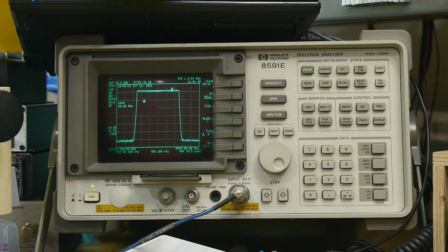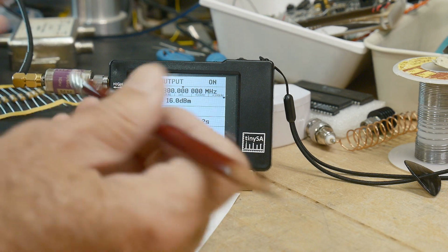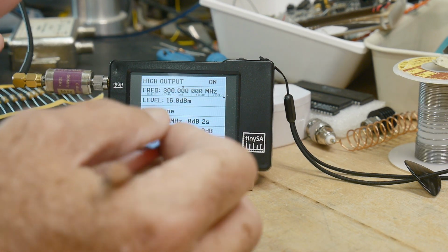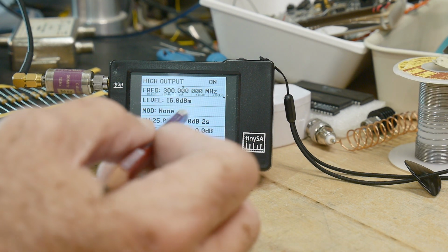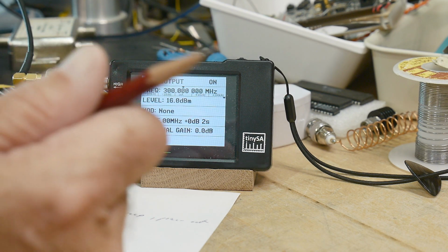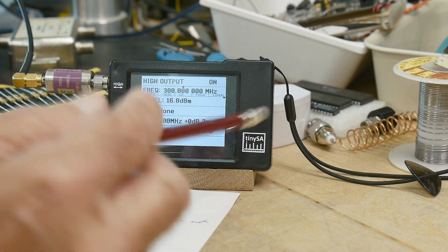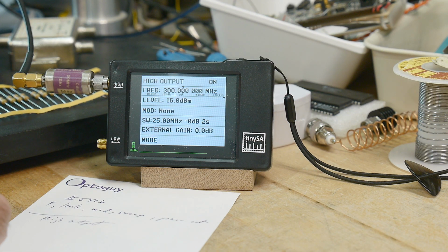All right, so I think that's all I'm going to show in the video here. It is a very nice RF generator. It comes for free with the TinySA, so you know, you can justify buying this just for the generator. Yeah, it does have some harmonics and stuff. The filtering isn't quite right. You'll get some out of band spurs and stuff, but it does cover quite a wide range.